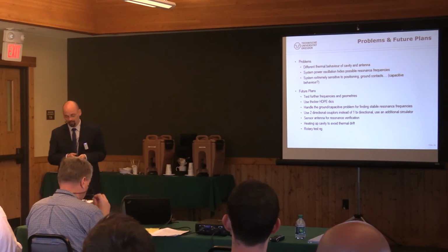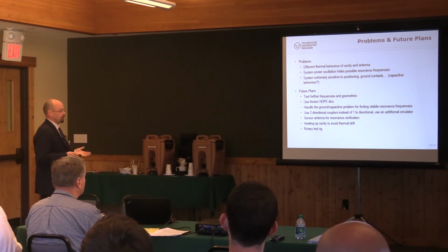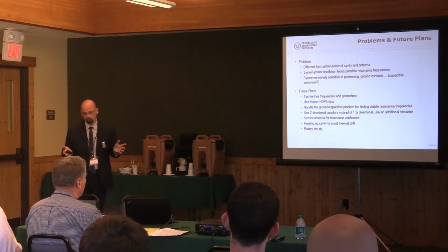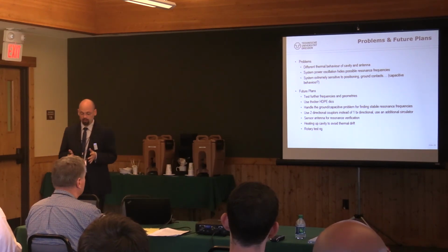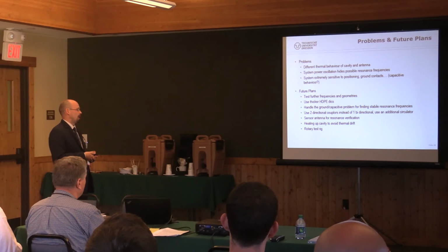I will replace this bidirectional coupler with 2 directional couplers. And perhaps the next step will be using a sensor antenna inside of my cavity to verify resonance frequencies or resonant behavior. A possibility would be to heat up our cavity to avoid thermal drift during the experiment, during the measurement. And yes, the next big step will be doing measurements on a rotary test rig.